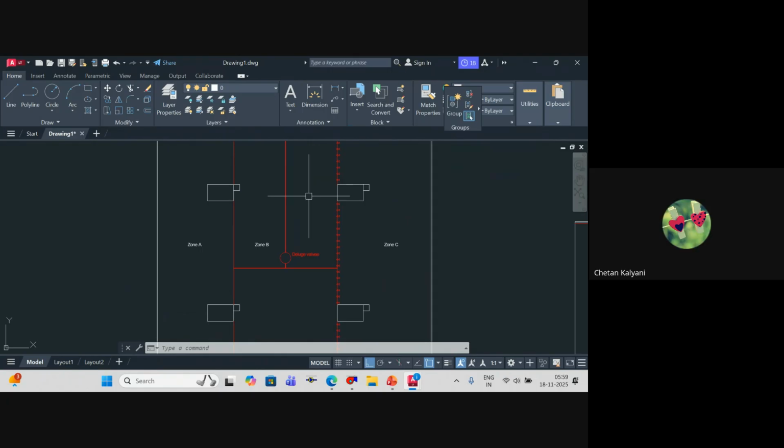Yes. So for that reason, up to the deluge valve, water will anyway be there from the pressurized firefighting pumps. But from the deluge valve to the nozzles, you will not have any such water, except in case of fire. So for that reason, after the deluge valve, we'll always go for GI piping. Understood or not? After deluge, it will be a very dry system, is it? Yes, it will be a dry system. Up to the deluge, it will be wet and pressurized. Post deluge, it is completely dry. Okay, clear.